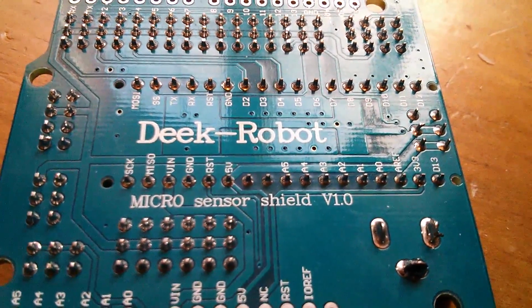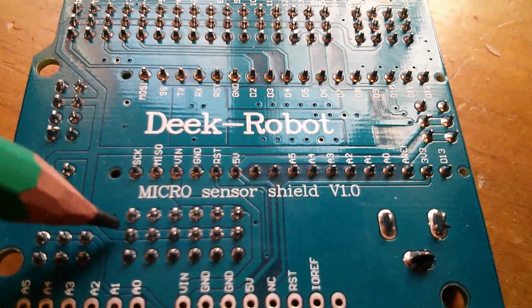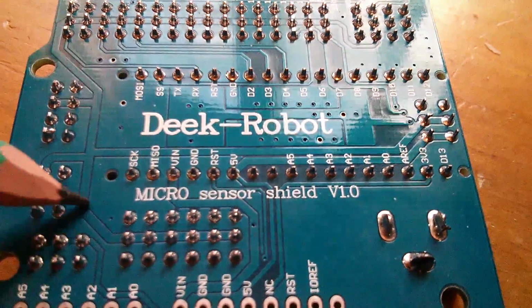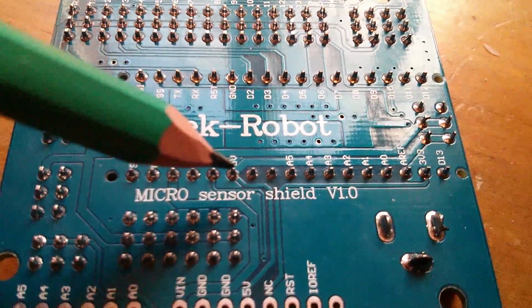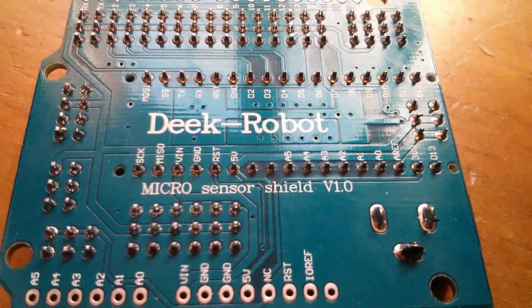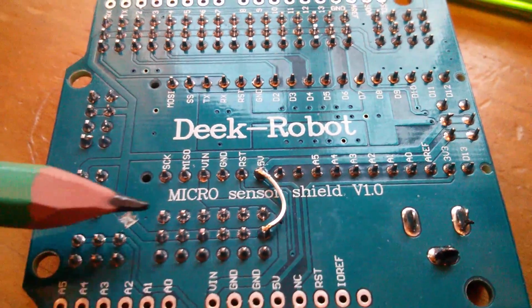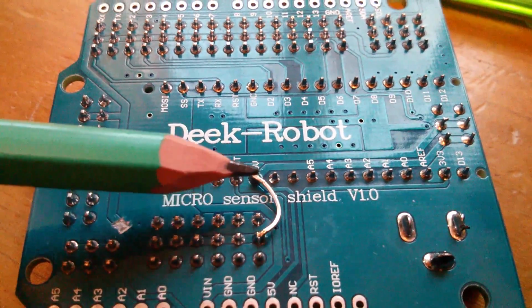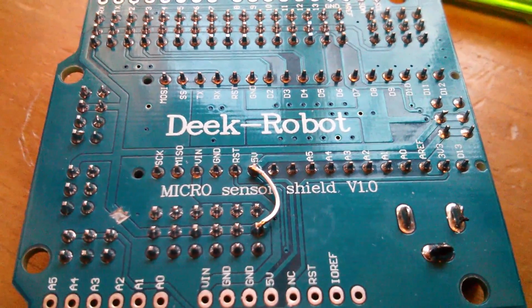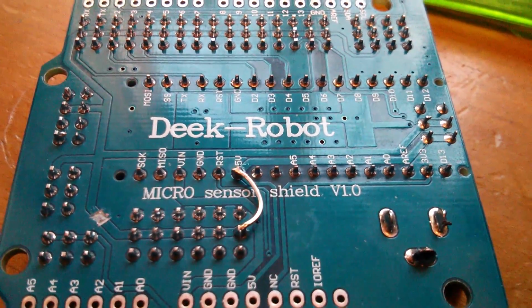And I can't see why I would ever want to take measurements using a VCC different to the reference VCC for the A to D. It doesn't make sense that this line is connected to anything other than analog 5 volts. So I'm going to make that cut, I'm going to make that change and modify this board. So there's my mod, a break in the track just there, and then a wire link running round to analog 5 volts, so that VCC for the A to D inputs is now always analog 5 volts, the same voltage as the A to D's reference.